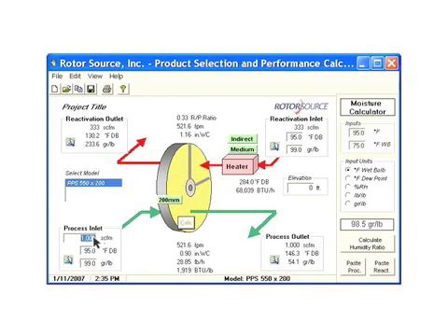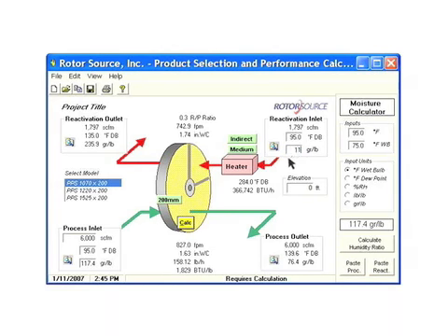In this case, if you were to treat the same 6,000 CFM of air at the same outdoor conditions of 95 degrees at 78 wet bulb, you would be able to get a unit selection similar to the other program. You can also change the air used for reactivation to make sure that you adequately represent the amount of moisture which is used. Once you've made a selection, you can also choose to use a high value of heat, which raises the heat and temperature, reduces the moisture, or you can choose to use a low value of heat, in this case 248 degrees, which gives a lesser dehumidification.